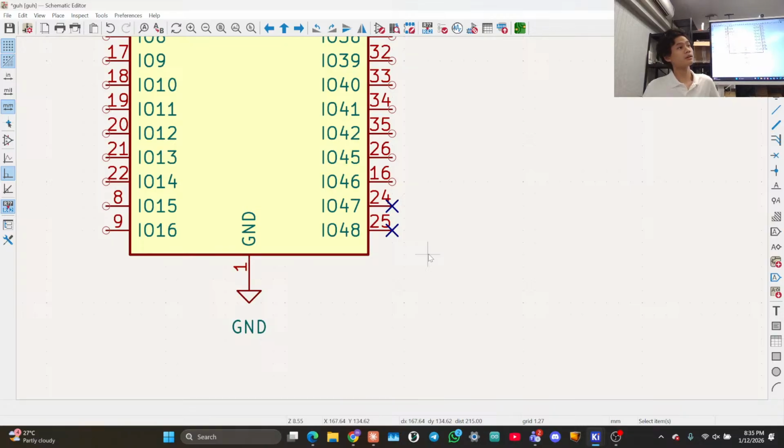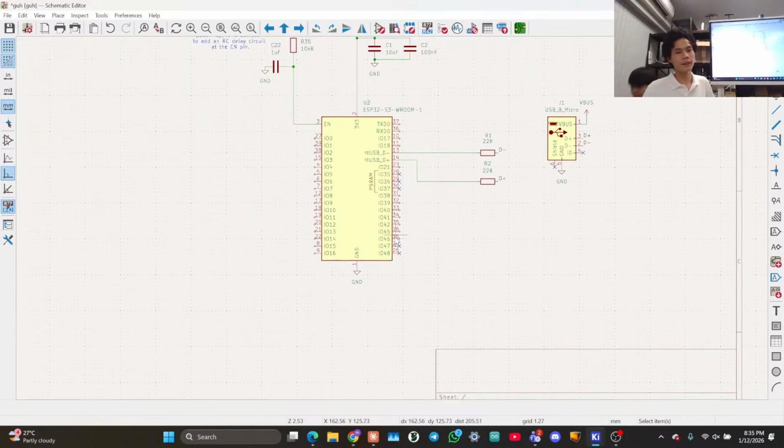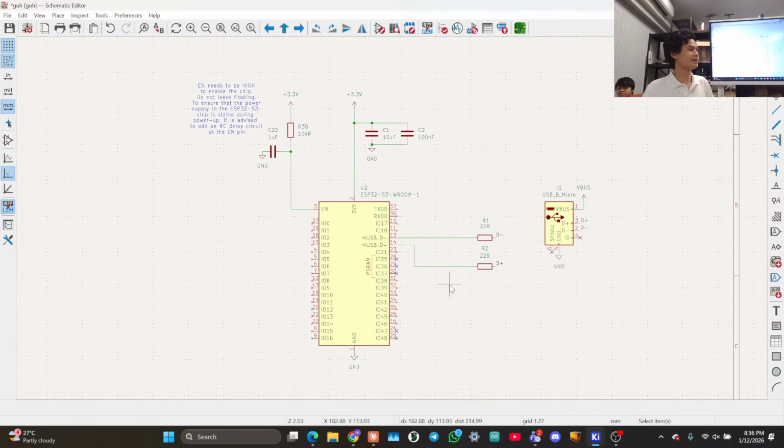1.8 volts. Some stupid low logic level, annoying. Most circuits are either 3.3 or 5 volts. You can find plenty of components which are 1.8 volts, but usually for hobbyists we don't bother. All your breakout boards are going to be 3.3 volts anyway, or 5 volts. This is for serious stuff, basically. 1.8 volts is for weird stuff you are unlikely to use. It's a lower voltage level, uses less power, and whatever. Nobody cares.